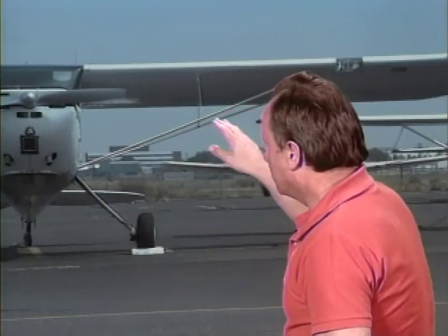Now, if the right wing of a monoplane is improperly rigged to a greater angle of incidence than the manufacturer's designated specifications, it will cause the airplane to be off balance both laterally and directionally. Now, when we're talking about too much angle of attack in the right wing, the airplane is off balance and it wants to roll. Now, rolling an airplane is expressed as being off balance laterally. And if the airplane wants to turn, it's off balance directionally.